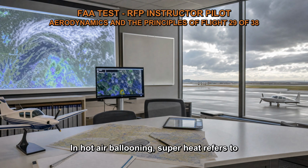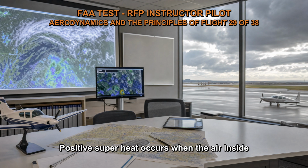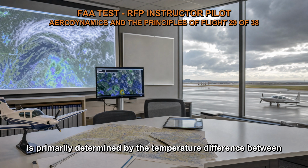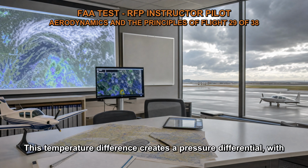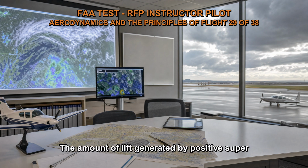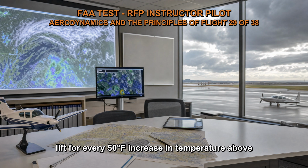In hot air ballooning, superheat refers to the temperature of the air inside the envelope being higher than the ambient air temperature. Positive superheat occurs when the air inside the envelope is hotter than the surrounding air. The lift generated by a hot air balloon is primarily determined by the temperature difference between the air inside the envelope and the ambient air. This temperature difference creates a pressure differential, with lower pressure inside the envelope compared to the surrounding air, resulting in buoyancy and lift. The amount of lift generated by positive superheat is approximately 1% of the static lift for every 50 degrees Fahrenheit increase in temperature above ambient.